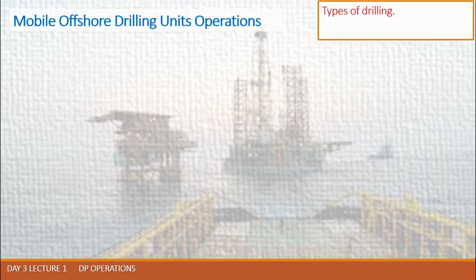DP rigs are currently configured to operate in water depths up to 2000 meters, with greater DP rating available in the future. Operating in such depths raises unique problems mainly relating to position reference. A DP rig needs fully redundant geographic position reference in addition to the riser angle feedback described above.